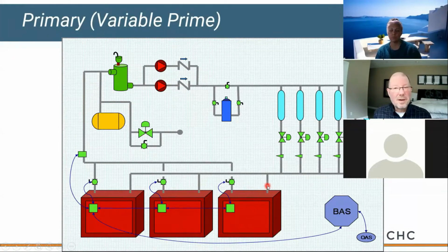And the other thing to think about, you're also going to split that flow by half for each chiller. So one condition you might need to look at is what's the minimum flow for each chiller? And do you account for that out here with a three-way, or do you go primary, secondary, and just put dedicated pumps on there? You certainly have an option.